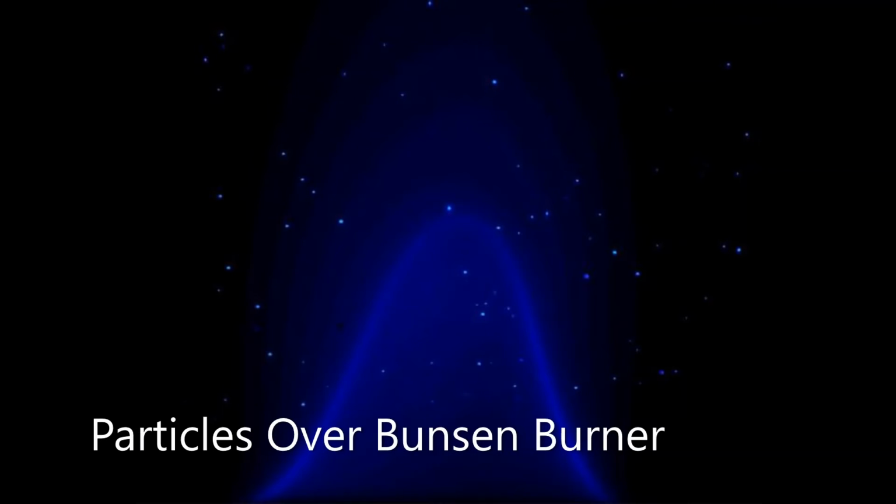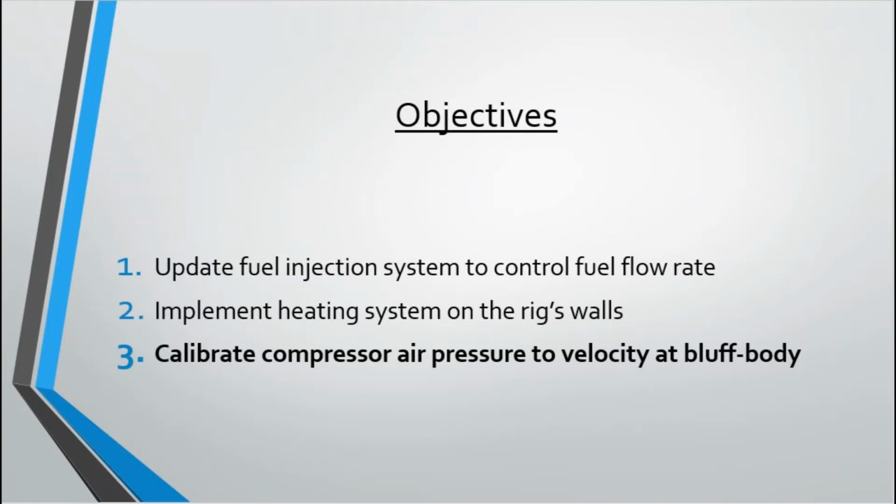This camera detects a light scattering called Mie scattering, which is from particles such as dust and, in this case, fuel droplets, whose size is much larger than the molecules of the gaseous fuel and air. If these images do not display these large fuel droplets, then that is how I will know that the heated air and walls are successfully vaporizing all of the fuel. The airflow entering the rig comes from a compressor whose pressure is controlled.